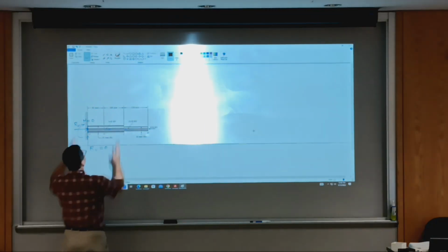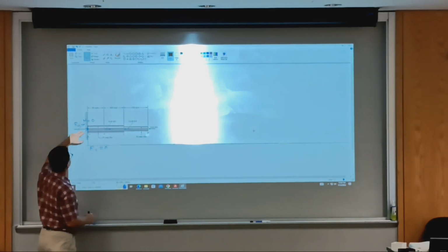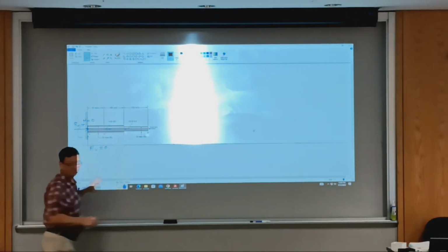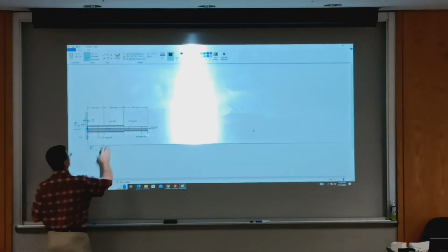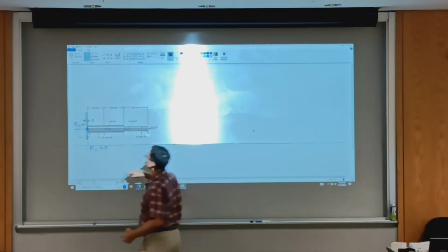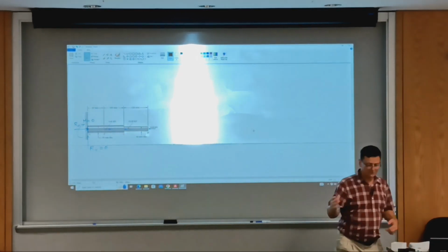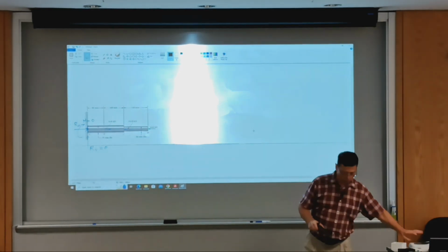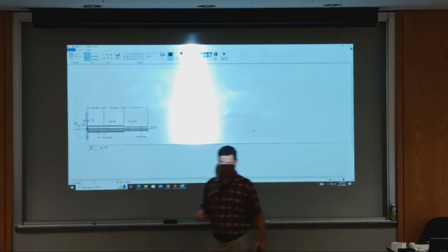We don't have any load that's perpendicular to the axis of the beam to cause the moment in the vertical load, or say you have a concentrated moment somewhere. We'll see this kind of problems later on when discussing beam bending. So this is just subject to some axial load, but the load is changing as you move along the column. And stress is likewise, and for other reason that the cross section changes.